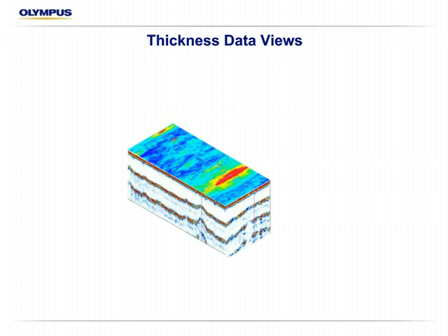It's also very helpful if we do have something like mid-wall laminations, to determine if they have any cracking or step-wise cracking in between them, or any other condition besides the thickness reading that might be useful. These other views really come into a big benefit for that.